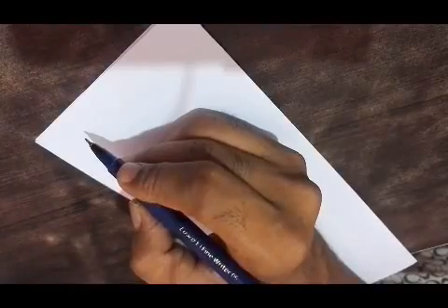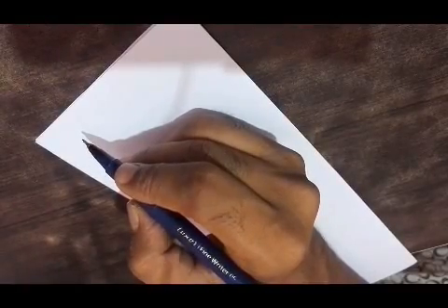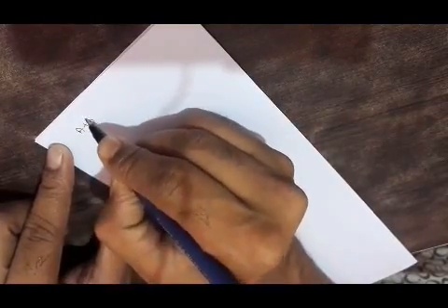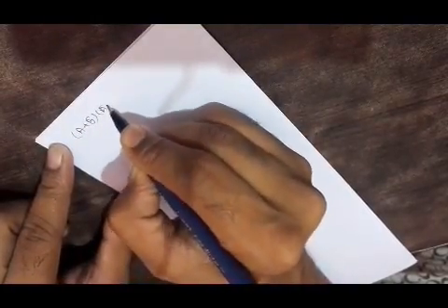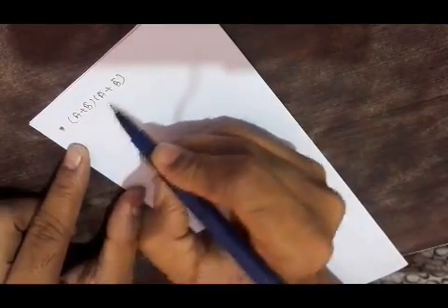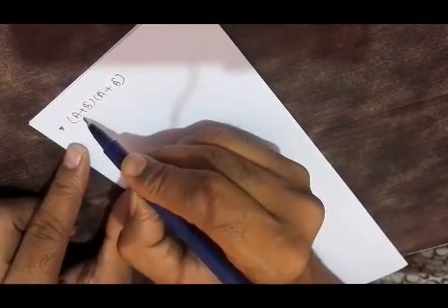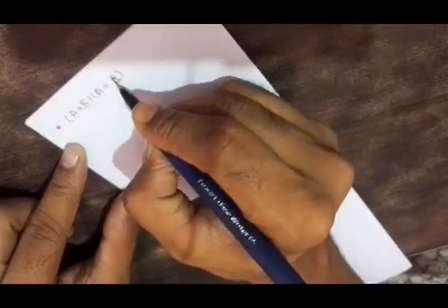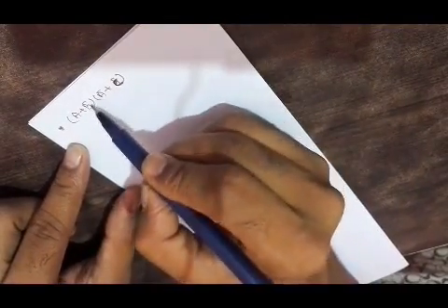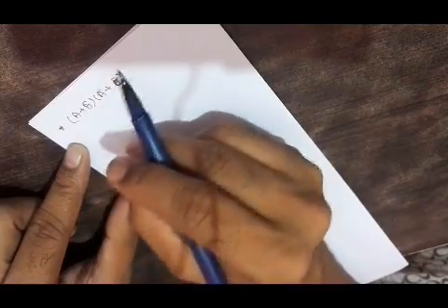This will help you understand why 0 0 0 and 1 1 1 are helpful. Okay, so let's start. We have A plus B bar and we have A bar plus C bar. This is a simple example just to save time. I'll discuss some important questions on all the topics I have been covering. So this is a minimal form. Why is this a minimal form? We can judge easily that this is a minimal form because we have 3 variables A, B, C, but each term has only 2 variables.